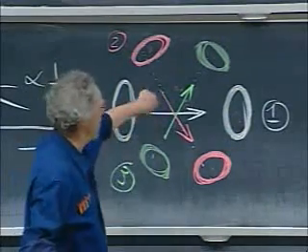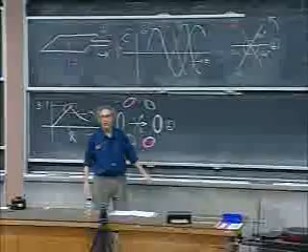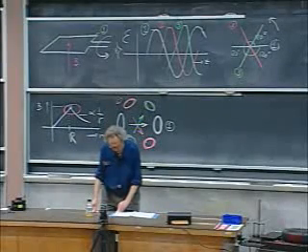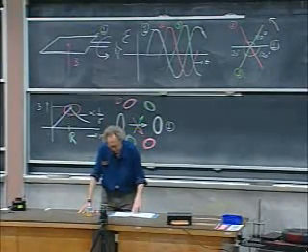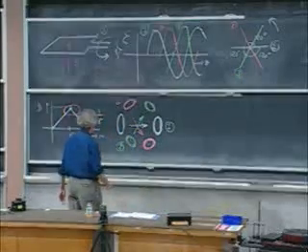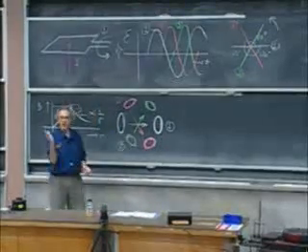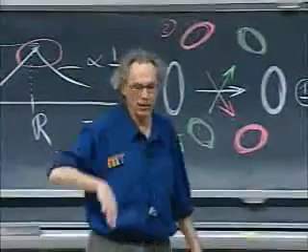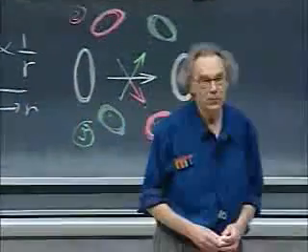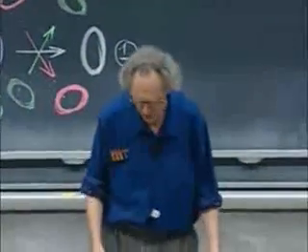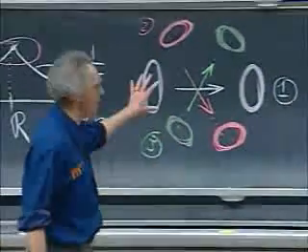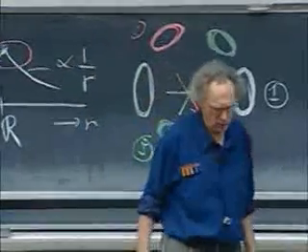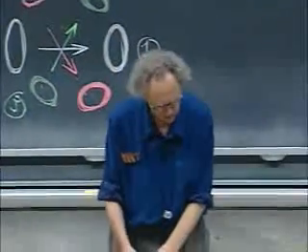Well, it rotates once around in the period of your alternating current. If that is a 60 Hertz current, then it will rotate around with 60 Hertz, 60 times per second. And so if we put a magnet in here, then this magnet will want to follow this rotating magnetic field. And we call that a synchronous motor. So the rotor of such a synchronous motor itself would be a magnet, and it would rotate around with the frequency of your alternating current. But you need a three-phase current for that, so that the magnetic field rotates.